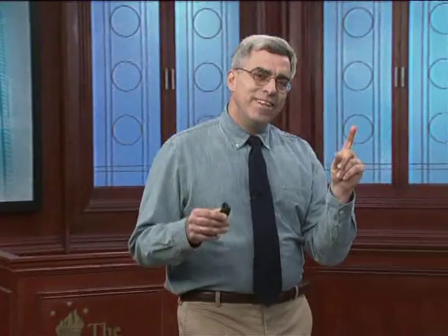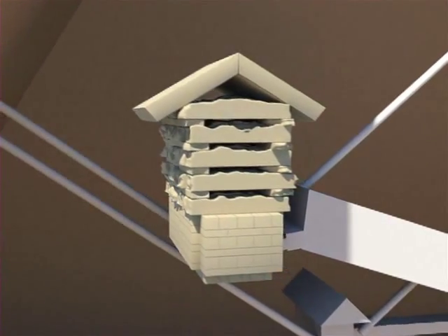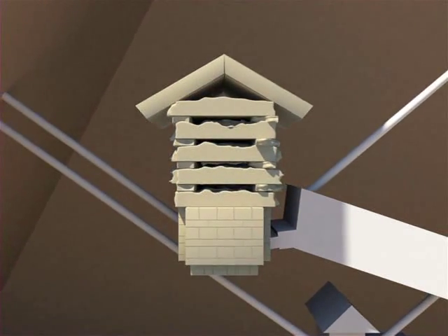But wait, when I calculated the stress in that roof slab, the only load I used was the slab's own weight. Aren't there hundreds of tons of stone above that slab also contributing to its bending stress? Well, no, actually not. Immediately above the king's chamber are 5 more chambers, stacked one on top of the other. When archaeologists discovered them, each chamber was completely enclosed. There were no passageways connecting them to anything else. They were entirely empty, and their interior surfaces were unfinished.